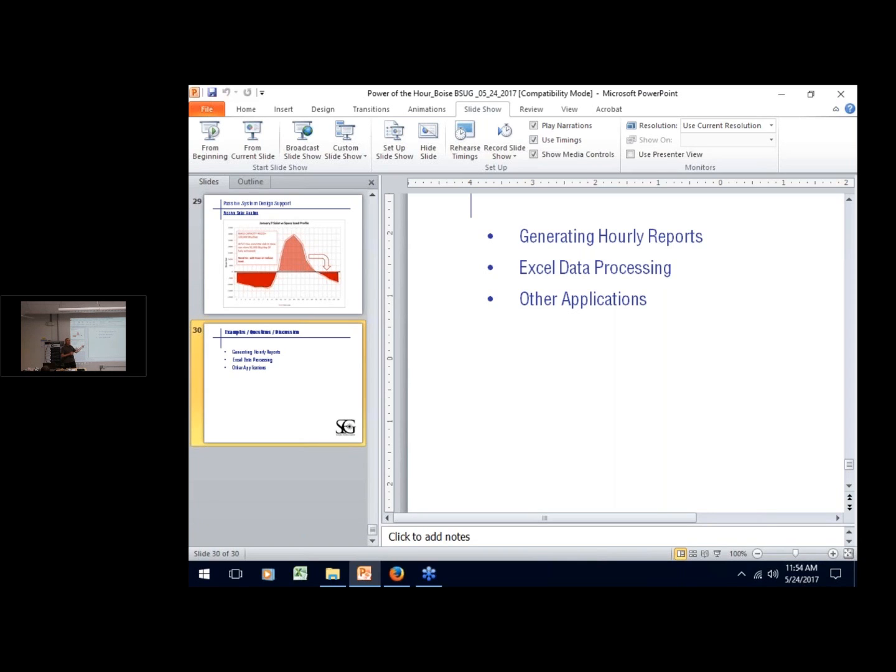In the Pacific Northwest, if you specify the summer solstice as your design day, depending on how you're modeling your glass, you will have wildly inaccurate peak solar loads on that design day, because your peak solar conditions are going to occur somewhere between the end of July and the middle of September, typically.